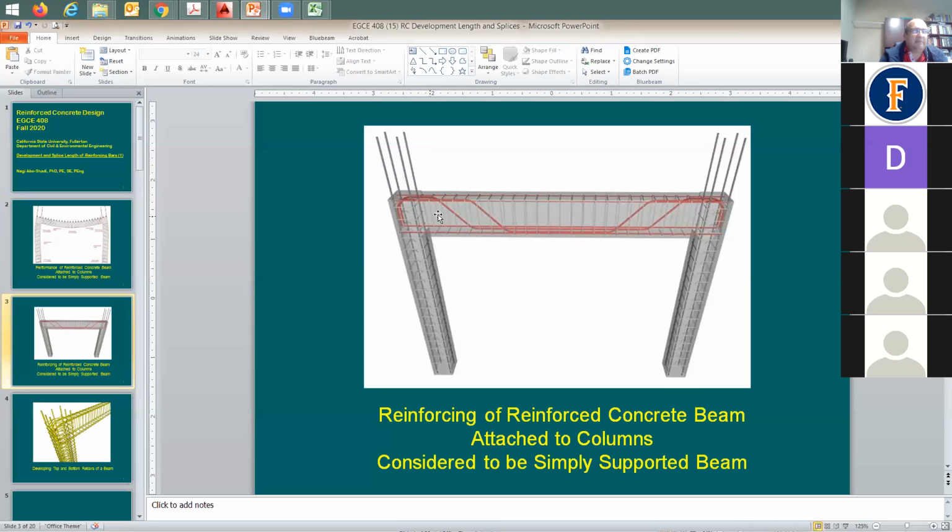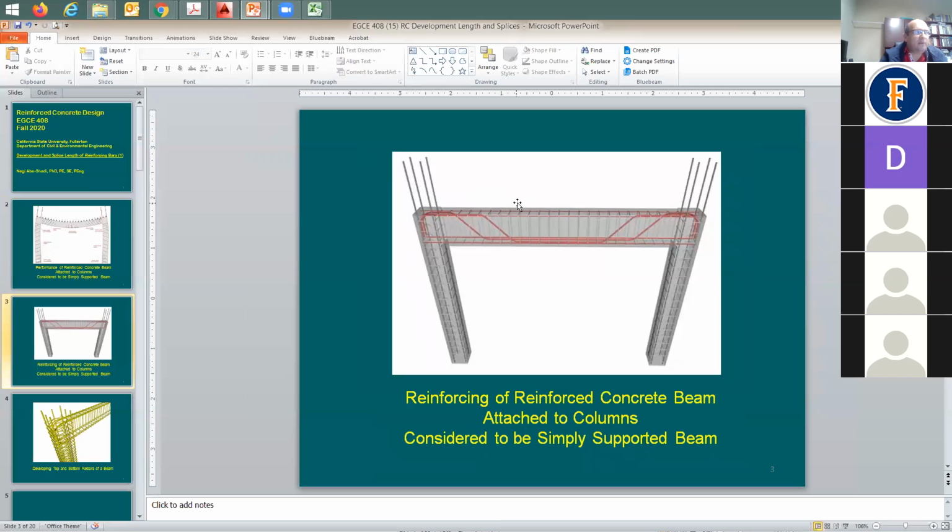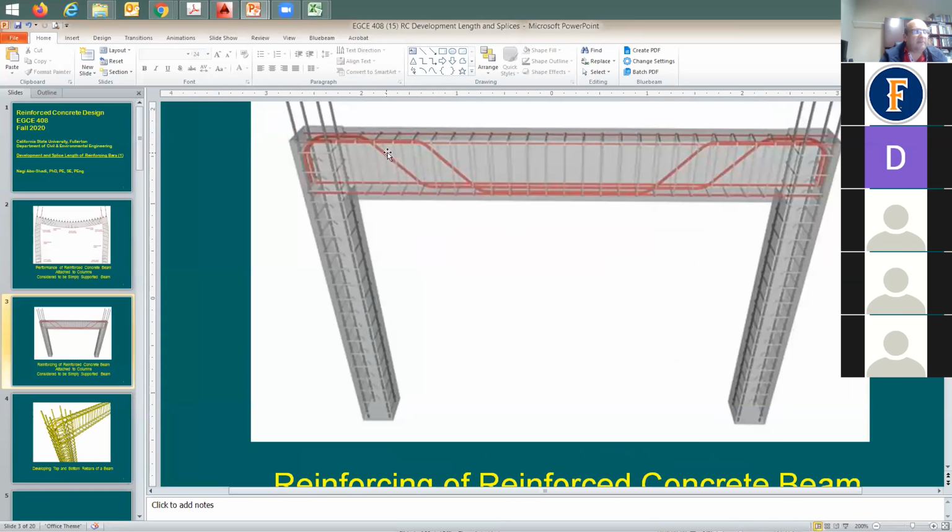But you know that because of this connection, you're going to have some cracks and you need to put in some reinforcing bars. So what you do here, like in this picture, you can take some of these bottom rebars, bend them, bring them up, and just leave them there. But there are no calculations for it. I see that, but in your picture, that tension rebar that goes horizontal, which rebar, the bottom or the top? The bottom. So that is separate from this hook rebar, correct?